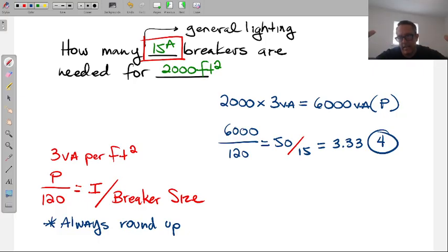And then try to evenly distribute the amperage through those. How do we control the amperage on these? Since I don't know what a homeowner is going to plug in, same amount of outlets per breaker. Don't put like 8 outlets on one breaker and 3 on the other one. You're potentially going to overload the one that you've put more outlets on, which is another way to limit amperage on a circuit. Just limit the amount of outlets you have.